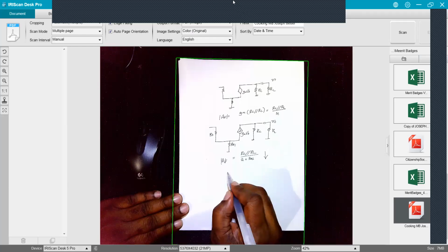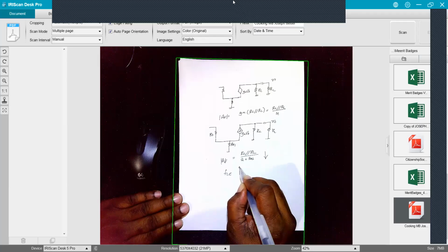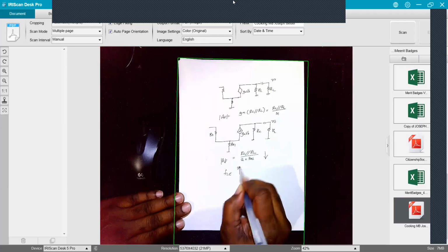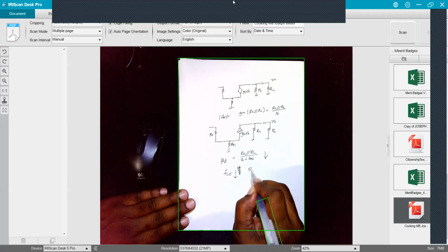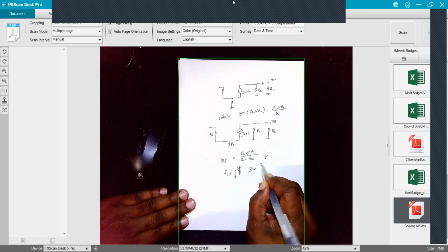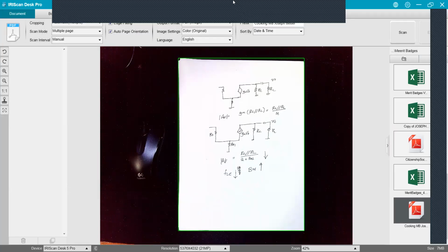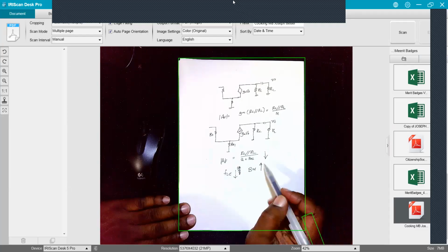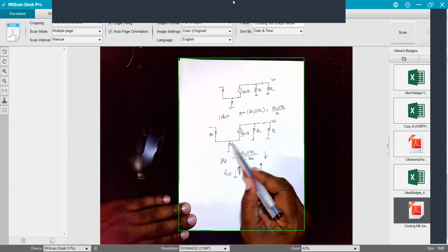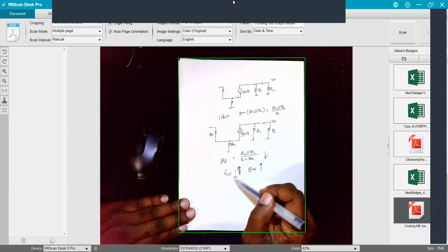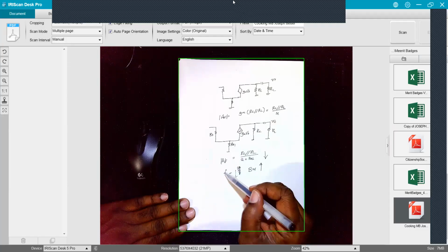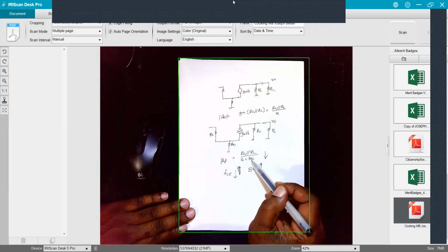But what it does for your F sub LE is it causes your FLE to decrease or go lower in frequency, which causes your bandwidth to increase. So if I wanted to, just adding this in and not completely bypassing it adjusted my low frequency pole, it also adjusts, or in this case, decreases my gain.